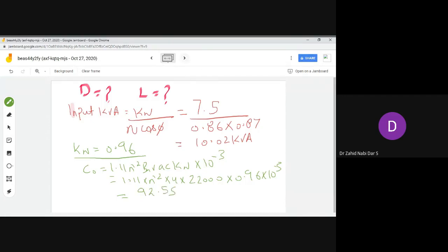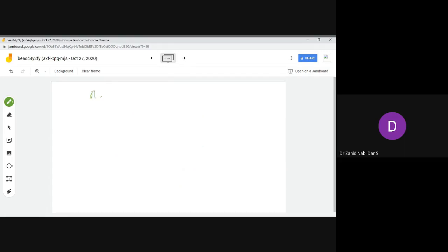Again, like the previous problem, you saw Ns is equal to 2f by P. So here again Ns would be equal to 25, because this is 2 into 100 divided by 4. Sorry, frequency is 50, so 100 by 4. This would be 25 RPS.